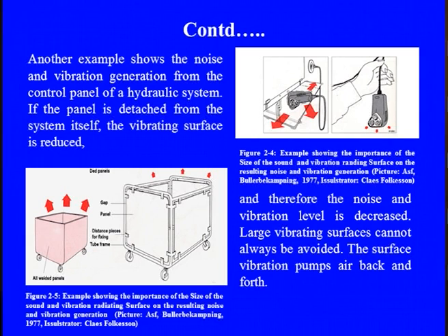The same kind of vibration, in terms of amplitude and frequency, is generated on the other side, in the hand, but the compressibility of air does not support it the way a solid structure does. So, you see very little propagation there. Similarly, on the other side, in this particular machine in which we have used vibration sources, when it has this solid support along with this part, it is immediately transmitted, and this transmission is so rapid that it simply amplifies the vibration and the sound together.